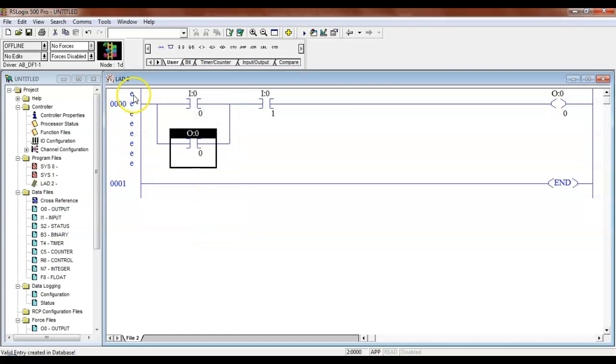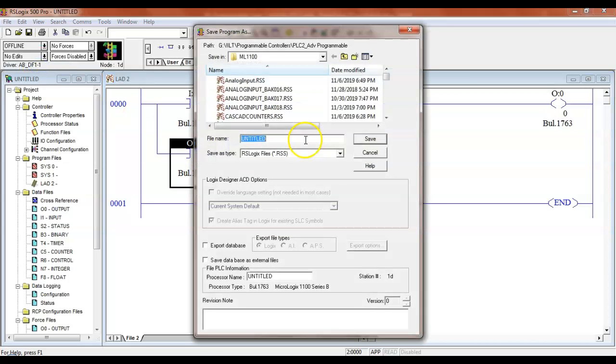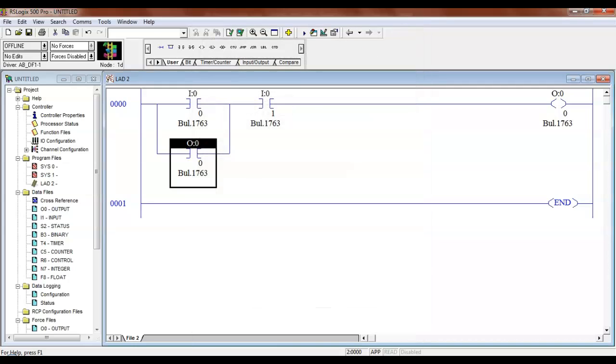Of course, it's telling me I had a syntax error. Now, why did I have a syntax error? Because there was nothing on the rung, and this one doesn't automatically clear. So what we do is we just check it. Okay, so 0, 1, 2. Then once I've got this written, I would send it to the PLC. Let me make sure it's out there first.